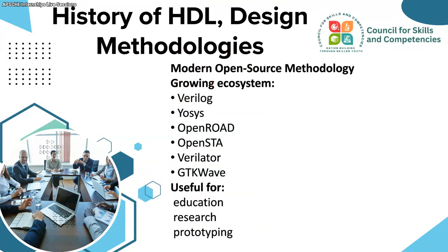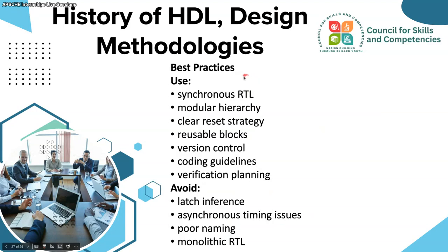Now let us get an idea of the modern open-source methodologies in the growing ecosystem: Verilog, Yosys as a synthesis tool, OpenROAD, OpenSTA, Verilator, GTKWave. They are used for education, research, and prototyping, and some are used industry-wide, since RISC-V came out. Once things are verified with these, people can go for proprietary tools.